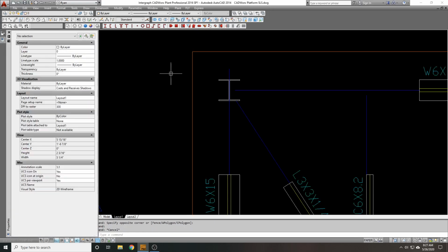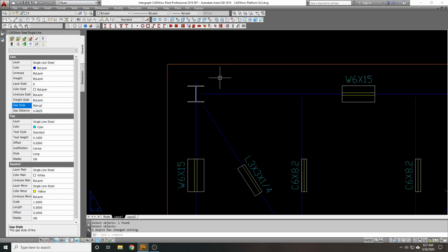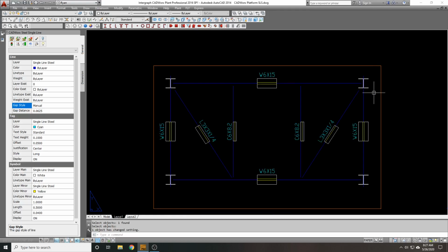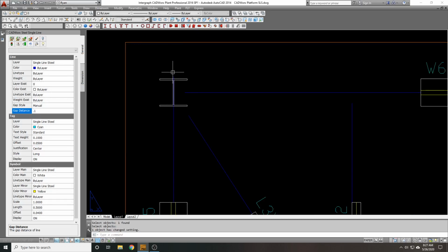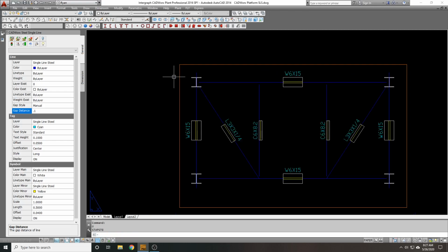I'm gonna turn this off. I'm gonna set the gap to manual, and I'm gonna hit apply settings. See how this got shorter? It got shorter because now I want to control the gaps for each one of these lines manually. I can set them all to, I don't know, 0.1, and you'll see they all get bigger. Even the ones at the end. There's no reason for this to be cut back, but it's because I'm manually controlling how much this line gets cut back. Automatic recognizes that.